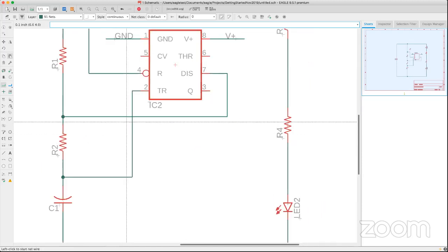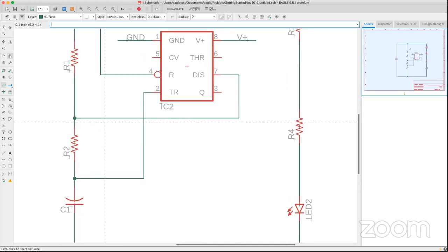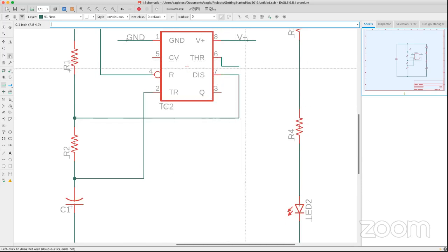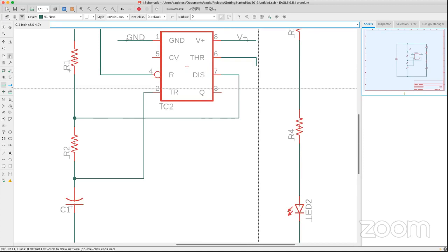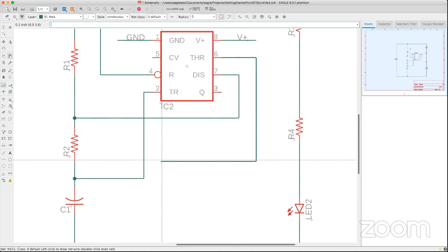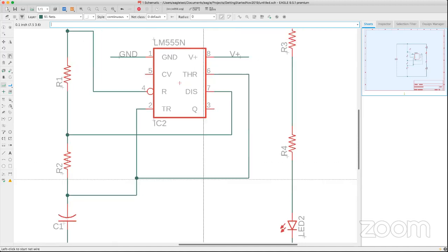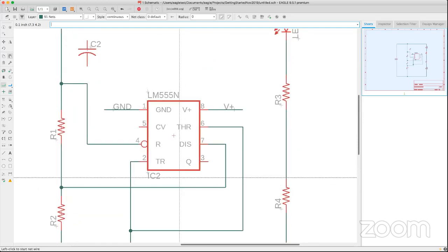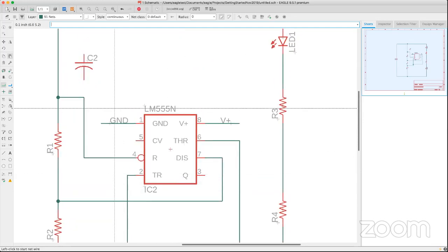Please notice that here I do not have a junction point, and here I do have a junction point. So this clearly identifies that these three lines have the same name. These are two separate lines. Okay, so there's a bridge there. Make sure that you know that. Make that clear. My trigger. I'm doing this a little different than when we did it the last time we hosted this.